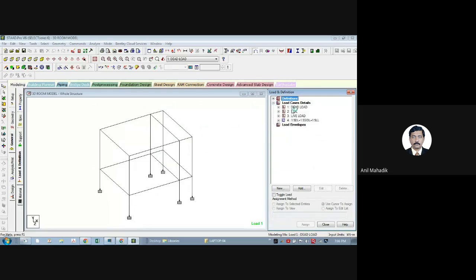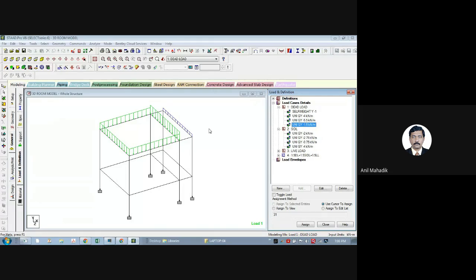So these were the loads whatever we have applied. We created the load cases, dead load, SIDL, live load, and combinations. And then we applied these loads per meter after calculation of two-way and one-way loads. So in this problem, I will delete these and let's learn how to apply two-way, one-way loads here. So let me save this first.